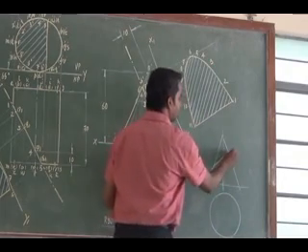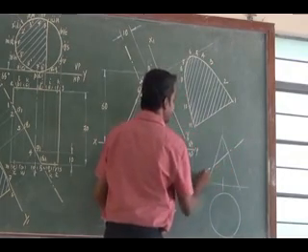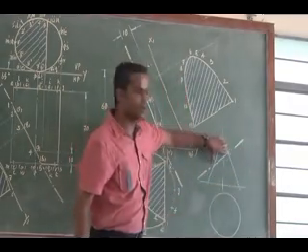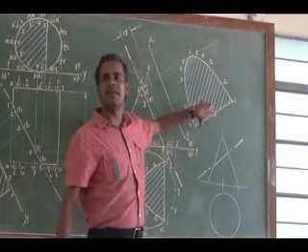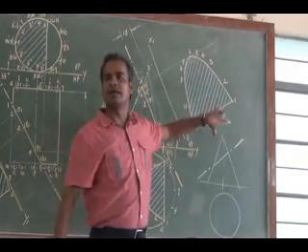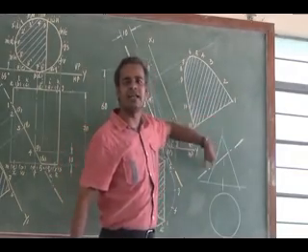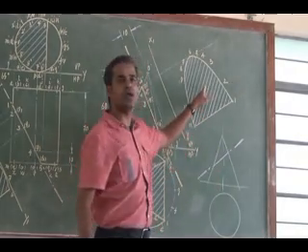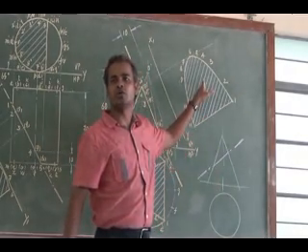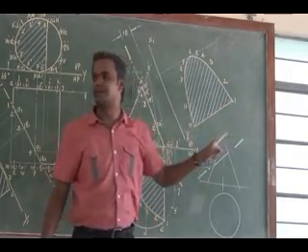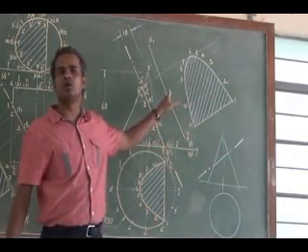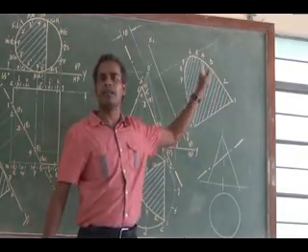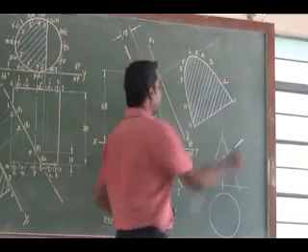If I cut the cone inclined to its axis, the true shape of the cut surface will be an ellipse. It cuts all the 12 generators, so you get 12 cutting points. If I project them into a true shape, that will be a perfect ellipse. Here, since it is parallel to an extreme generator, the true shape will be a parabola. So you have to get a parabola here.